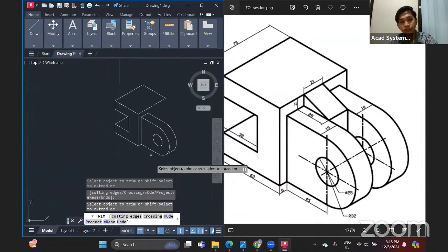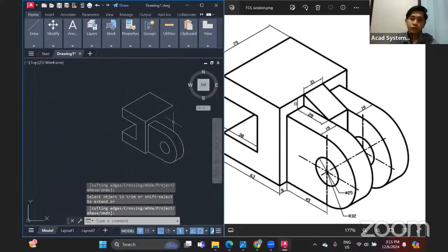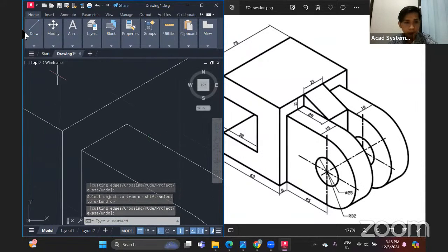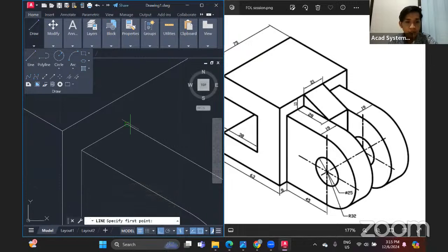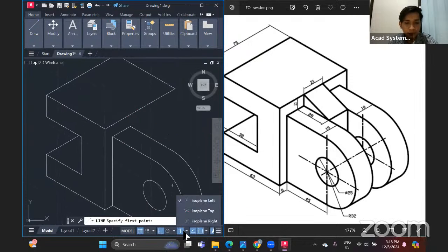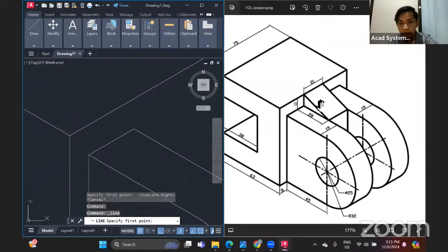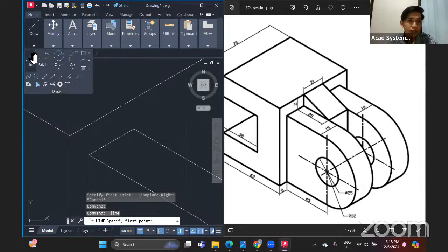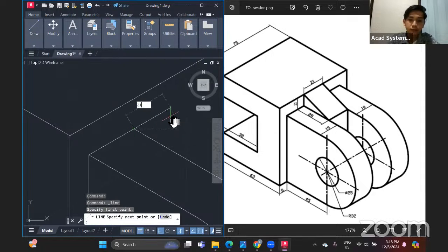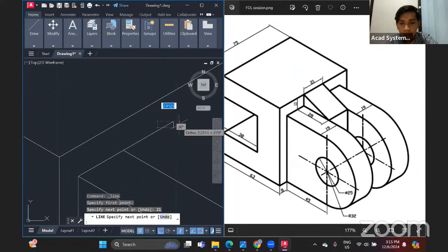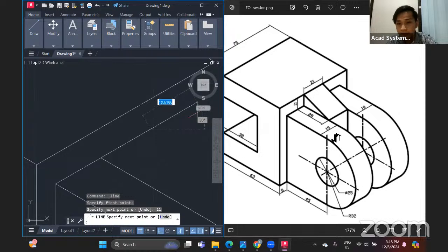As you can see, the first object here is already done. Then let's move on to the other object. Okay, so choose the line tool here and make sure to use the correct plane. The length of the center of this triangle is 21. So drag it to 21. Then make the second line for this part. We're going to drag it to 19 because the length is 19.